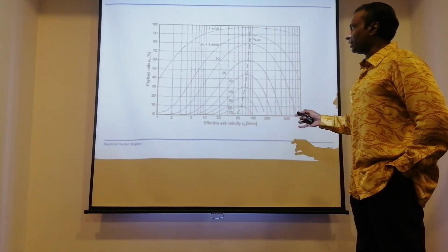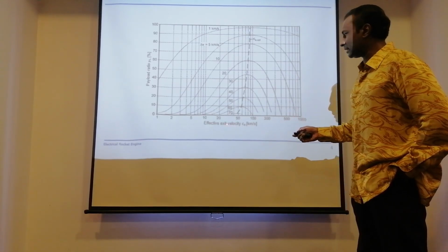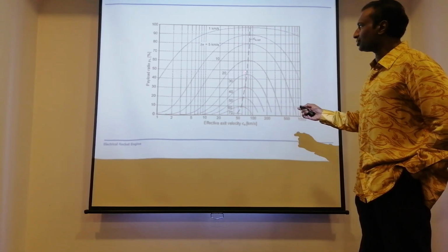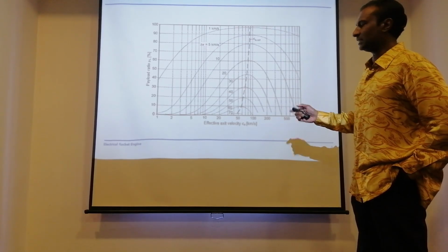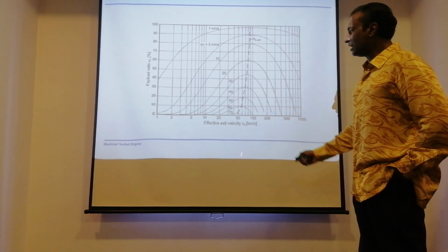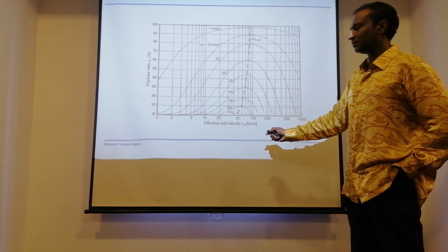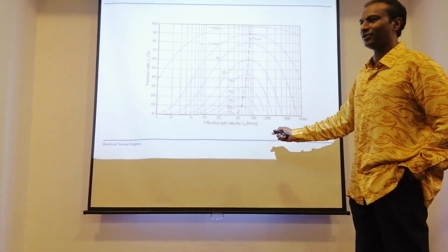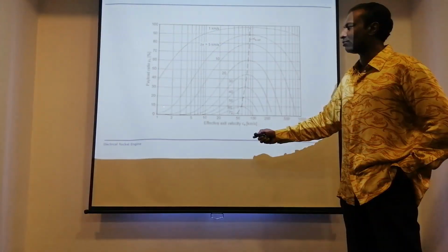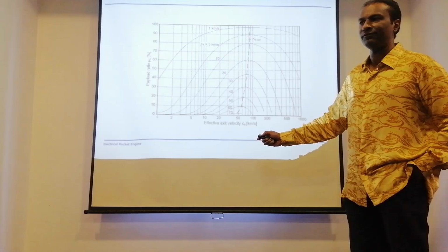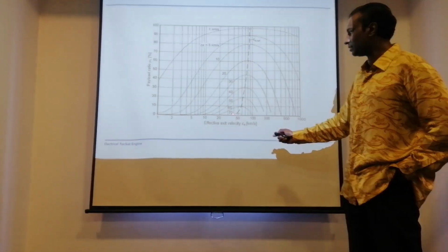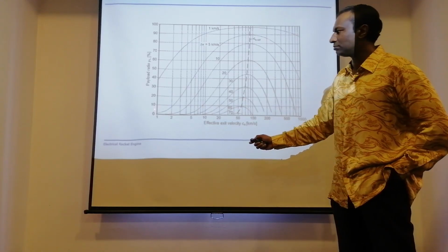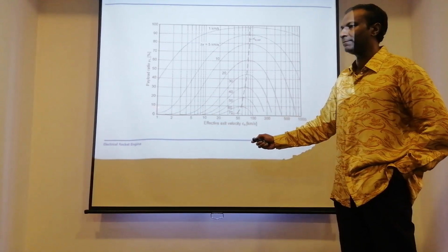What you have here is an average of the peak for all those cases of delta V. Now, if you want a very high delta V, that means you are very heavy, and the payload ratio is not going to be high. You are carrying a very small amount of payload. The delta V is very, very high, but the payload goes very, very low.